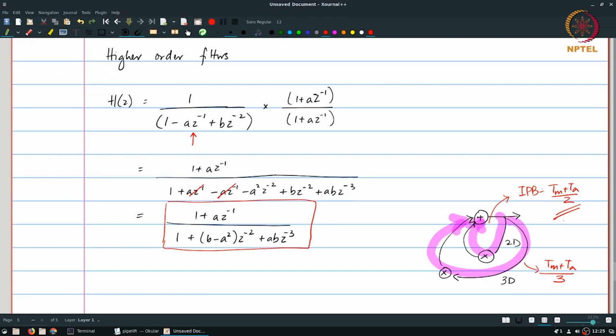On the other hand, if we have further domain knowledge, in other words, when we know that we are actually doing mathematical multiplications and additions, as in the case of the IIR filter, we can use certain properties of those particular mathematical operations to change the algorithm that is being implemented. The resulting algorithm, in certain cases, if we have done it right, can have a lower iteration period bound and therefore a lower sample interval than the original structure that we started with.